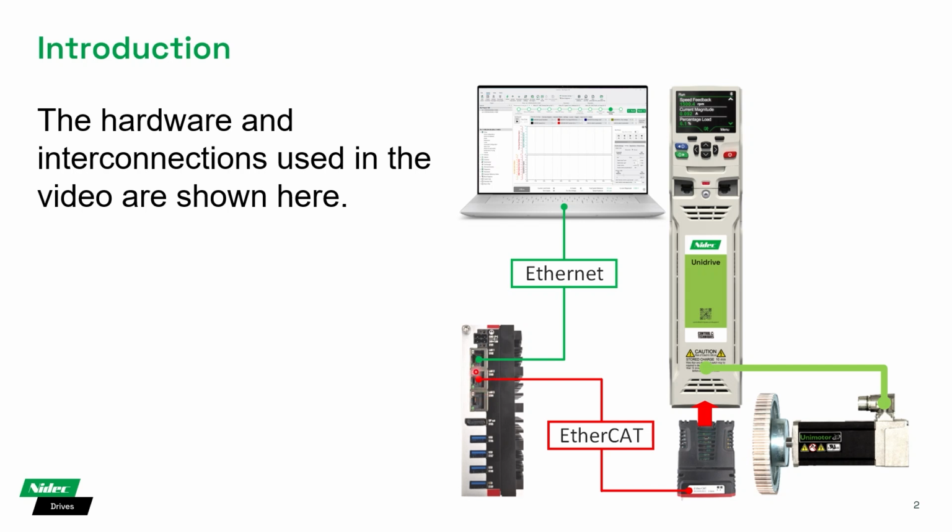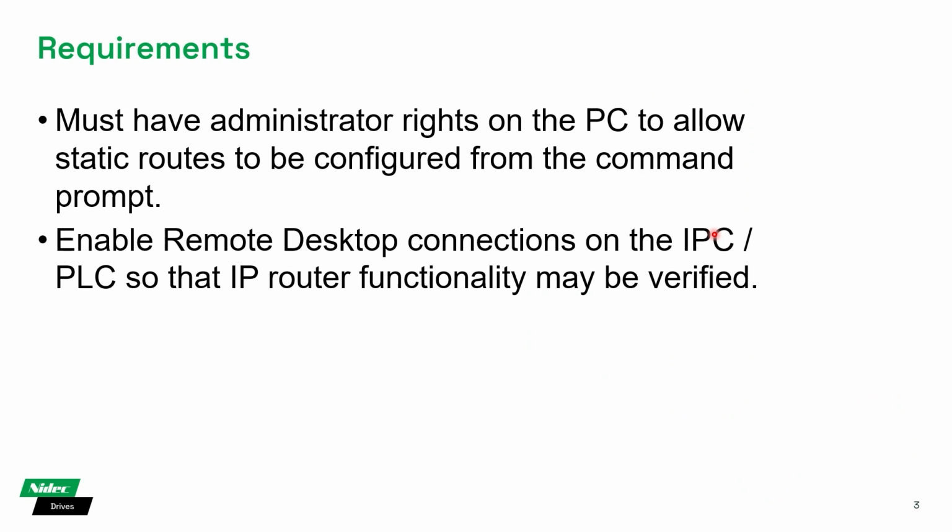One of the ports has been configured for EtherCAT connectivity, and we've got a cable routed through to the SI EtherCAT module, which is then plugged into this drive, which is a Unidrive M700, making it an EtherCAT capable drive. Now, if you've got one of our dedicated servo products, such as the Digitax HD M753, this interface is actually built into the product. However, the steps that you would follow in order to get an EoE connection working would be identical.